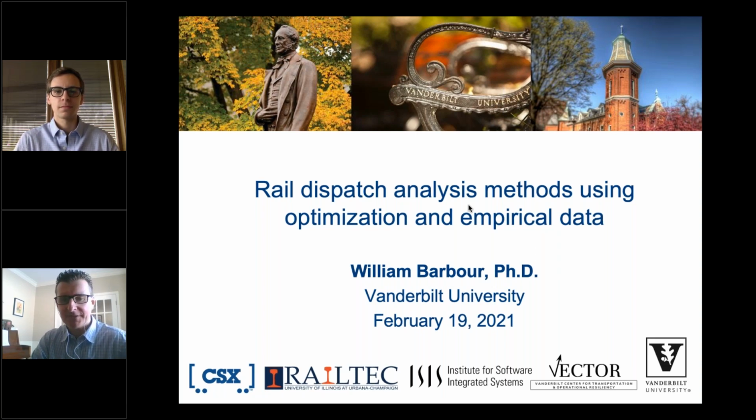Okay, today's seminar is going to introduce a very important topic, and a major factor in railroad operational efficiency and punctuality is the quality of the train planning and dispatching. The work presented today proposes a methodological tool set called the dispatch analysis problem that can analyze recent empirical train dispatching data against an optimal dispatching plan. A multitude of questions can be answered using this approach, such as the effect of dispatching actions on the optimality of future planning, corrective actions to mitigate the negative impacts of past dispatching errors, and identifying trains that introduce secondary effects to other train plans.